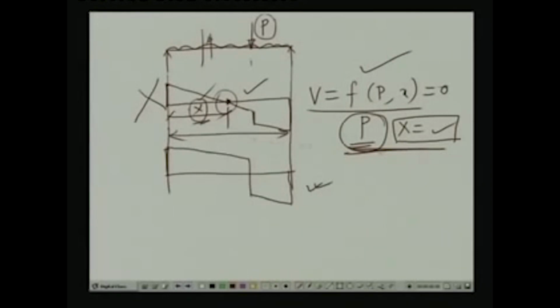That means the shear force does not cross the baseline at an intermediate point before this loading P. Hence, this particular diagram will be applicable in this case, and this is the point where we expect the maximum bending moment in the beam. We compute the maximum bending moment at this particular point, and correspondingly we find out what the loading could be.